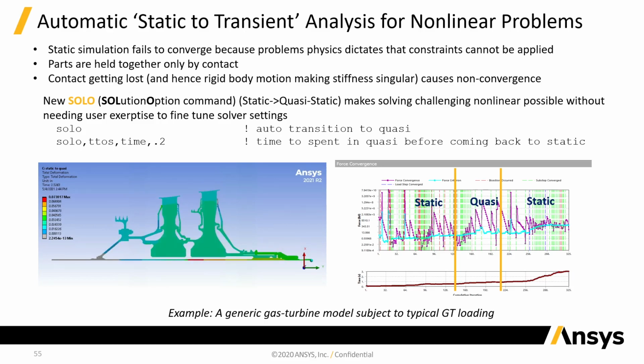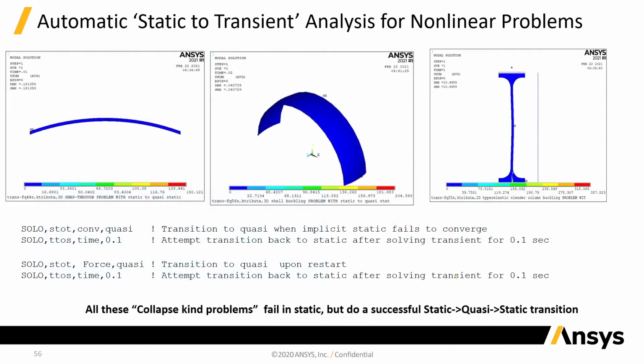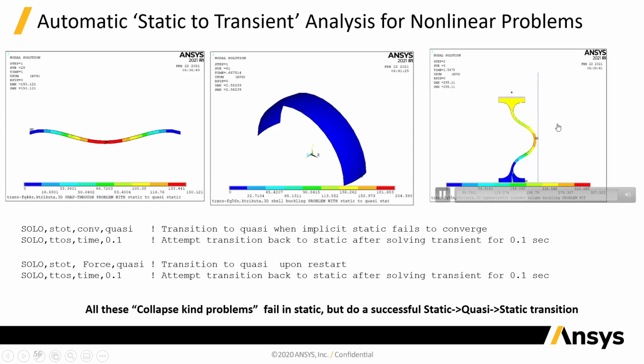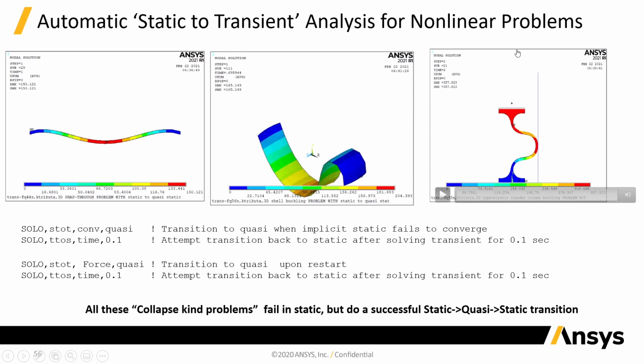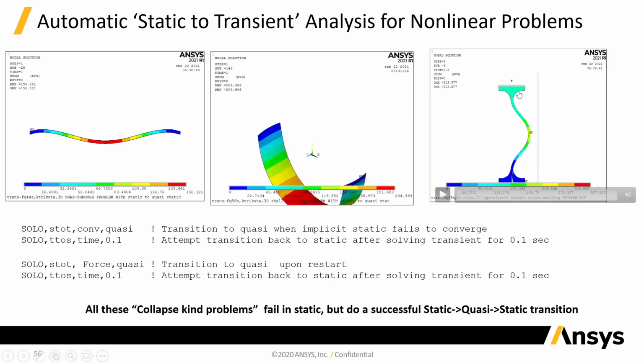So there's an automatic switch when you get instability, and that instability, as I said, could be caused by contacts or could be caused by some buckling. For instance, if you look at the movie on the right, we can see that this structure buckles, and then whilst buckling, eventually it will actually contact that plane on the right, and when it touches that plane, of course it stabilizes again, so then the dynamic solution can automatically switch back again to the static solution.